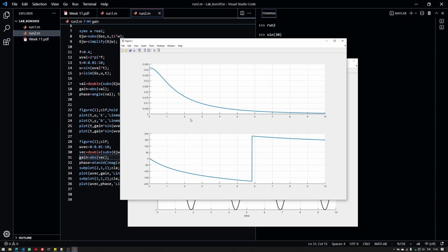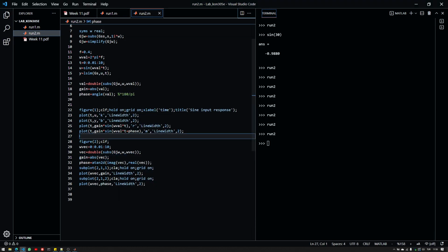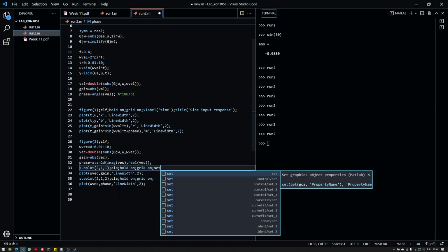You can see that this does not really look like a Bode plot, and you would be right there. But the reason behind that is that we have linear spacing in the x-axis, which is not the case for Bode. Since this is a logarithmic plot, and if you have a Bode plot, you should have also a logarithmically increasing x-axis. So therefore, we have to use a little workaround here.